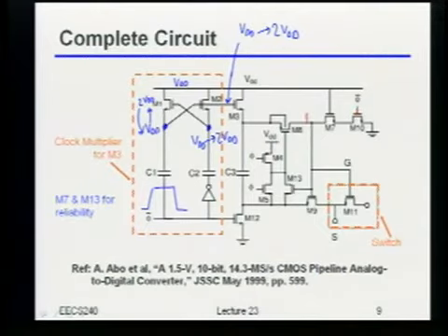There we go. Yeah, that's exactly it. Basically, in the worst case, this point is going to go up to 2 VDD. If that goes up to 2 VDD, the source of the cascode is going to be over there. Well, the gate of that cascode is at VDD, so there's no way that it is going above VDD. So if I look at the cascode device, it's got VDD across one side and 0 volts across the other side. My bottom switch has only got VDD across it, and so nothing is going to be overstressed.